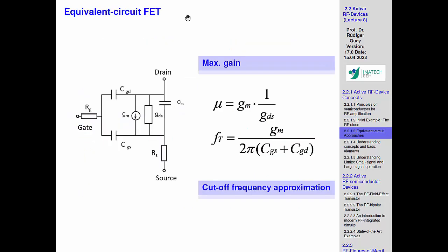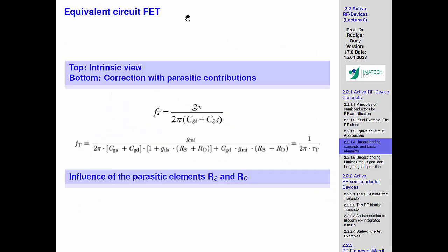Yeah, so that is, I think, okay. Why we are discussing this a little bit further is that at the frequencies where we are at, there's also a lot of parasitic influence. And you see the real cutoff will be lower than what you would generically get from the intrinsic device, because you have all kinds of corrections. For example, what I just talked about, there's a proportional reduction by the contact resistances at source and drain.